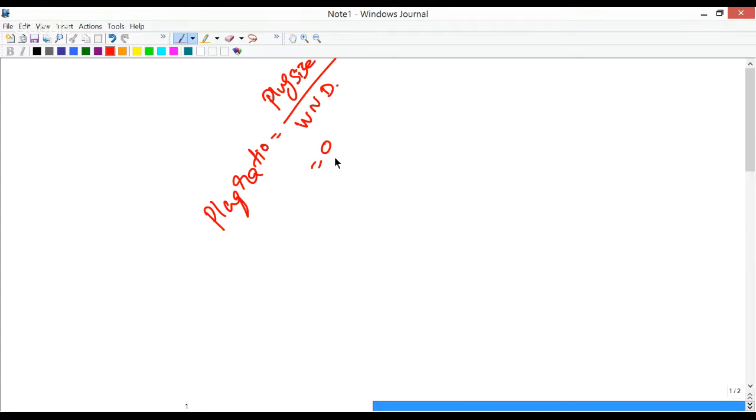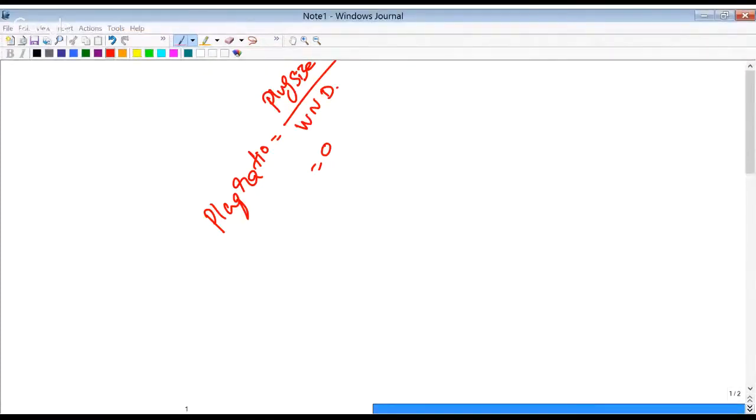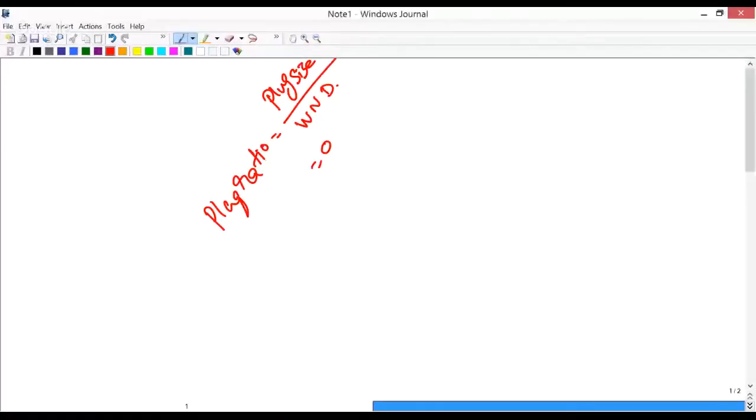is, which mode of laser beam welding is preferred to achieve increased depth of penetration? So obviously the keyhole. I also showed a lot of videos which we recorded using laser beam welding, right? So the keyhole stability is a function of vapor pressure during overlap welding. We discussed in detail. So the best mode of achieving increased penetration is through keyhole formation.